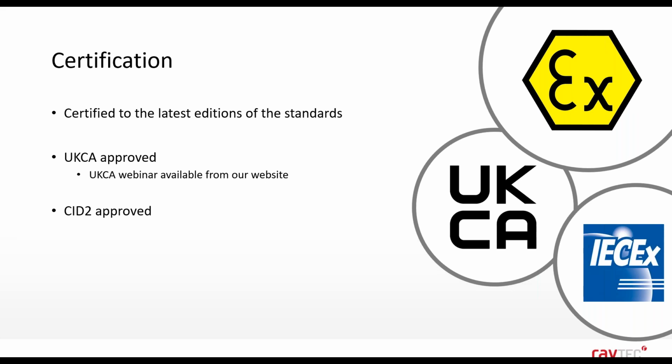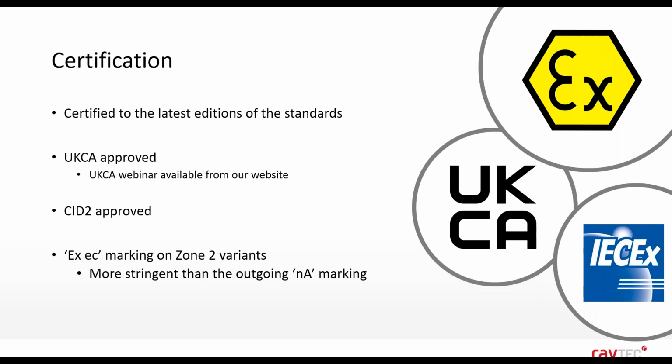But just looking a little further and specifically into the fact that it's certified to the latest editions of the standards, it also means that the Zone 2 variants are certified using the EXEC marking as opposed to the outgoing EXNA. So again, this isn't as relevant for the Class 1 Div 2 side of things, but certainly for products certified for use in the UK and Europe and anywhere that uses the ATEX classification, and EXNA, or sorry, I should say EXEC, is a far more stringent protection concept, which other manufacturers may struggle to obtain with older products using an older design. So that's something to bear in mind as well.